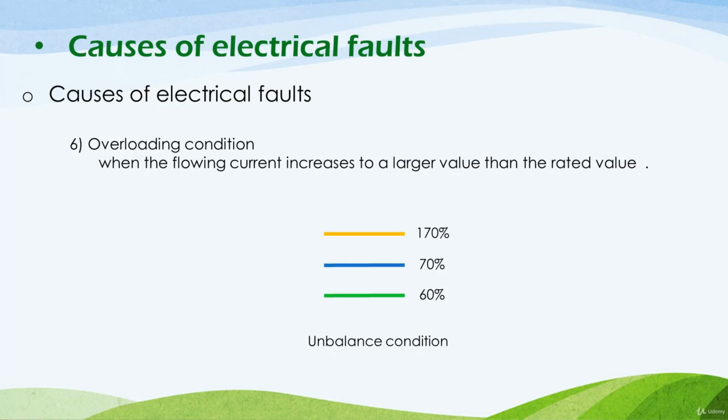So the cable is designed with a cross-sectional area and a specific material to carry only 100%, but it is now overloaded with a very large value, which is larger than 1.5 times its rated power. So in that case there will be a failure in that phase, as its insulation will be broken, and it may also be damaged or burned out due to the excessive power that this phase cannot withstand.